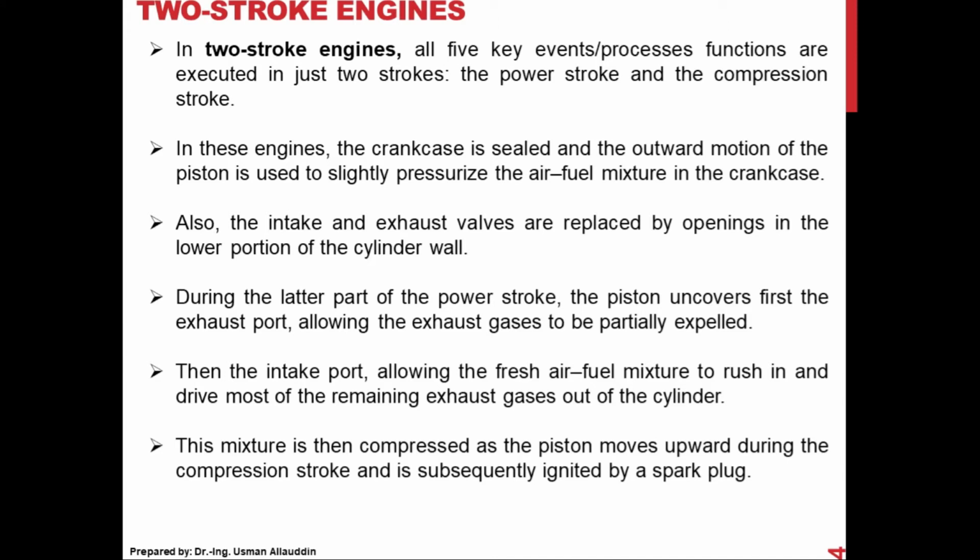When the piston reaches the top dead center, the spark plug gives the spark, ignition takes place, and the exhaust gases are formed. These gases push the piston downward from top dead center to bottom dead center. Volume will increase and pressure will decrease. This is the power stroke or the expansion stroke. During the expansion stroke, forces are exerted on the piston. The piston is attached to the crankshaft with the help of the connecting rod, so this force is transmitted to the crankshaft, and the crankshaft rotates and the vehicle moves.